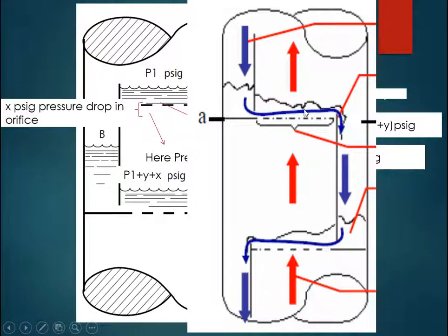So there is a liquid head gradient, and because of that liquid flows in this direction, and ideally that gradient should be very small. But if there is a liquid head gradient, and the vapor pressure below the tray is only slightly in excess of the weight of liquid, then in some part where the liquid height is high, liquid will start dropping, because the weight of the liquid there can't be balanced by this much excess pressure. That is what I used to think.